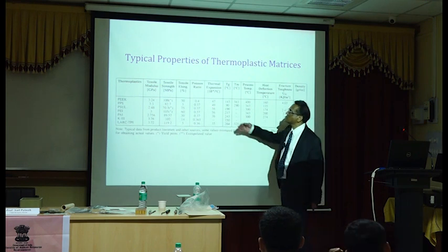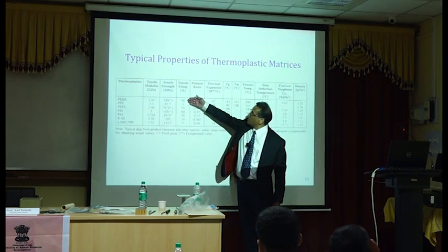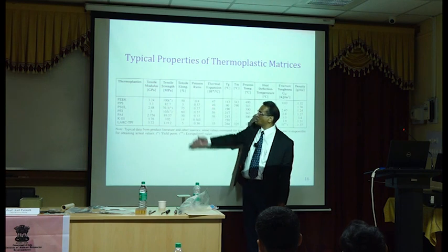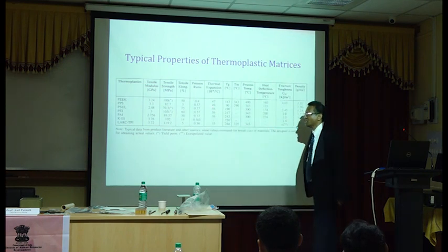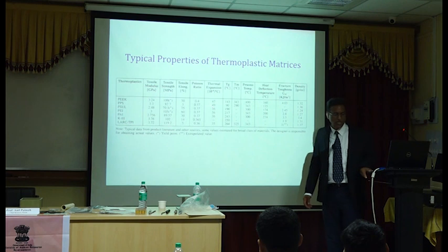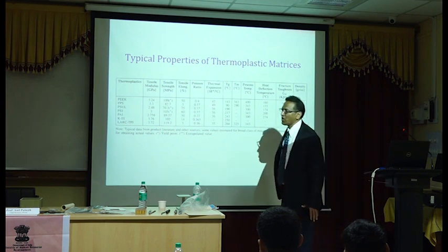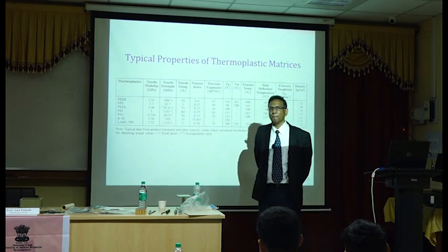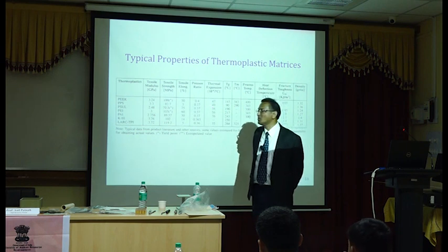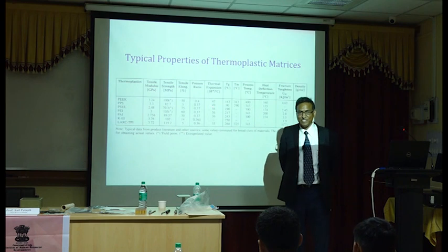So look at the tensile elongation, very large elongation. If you have very large elongation, give me one or two applications where your large deformation or elongation will help. Absolutely. Anything that is subjected to impact or dynamic loads, if you are able to elongate, you will increase ductility, right?